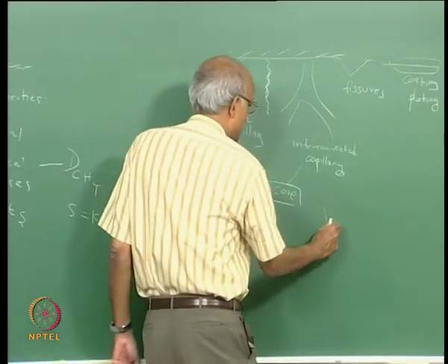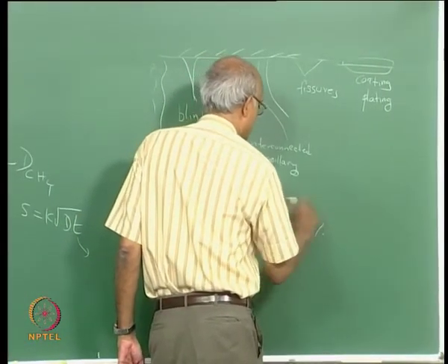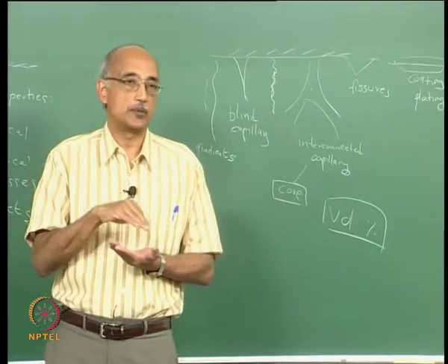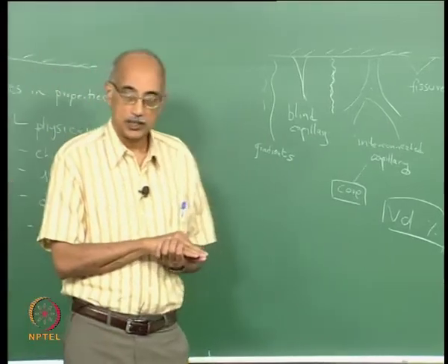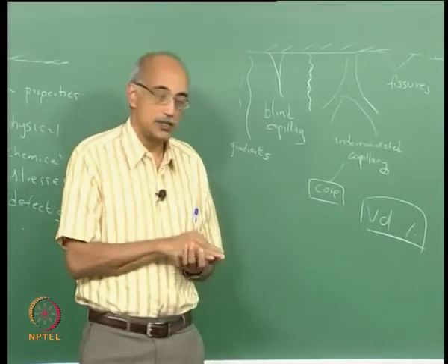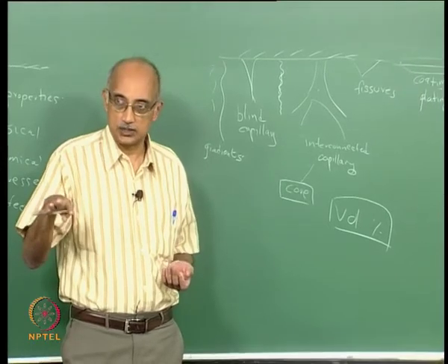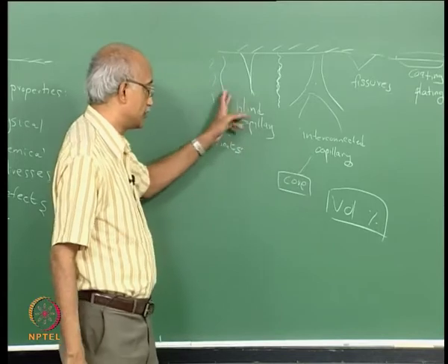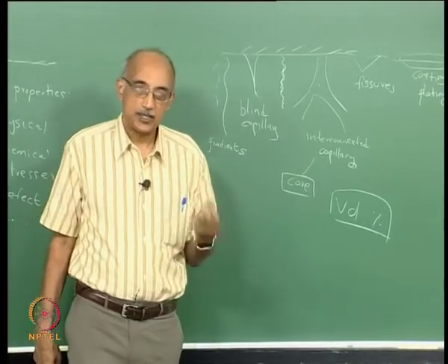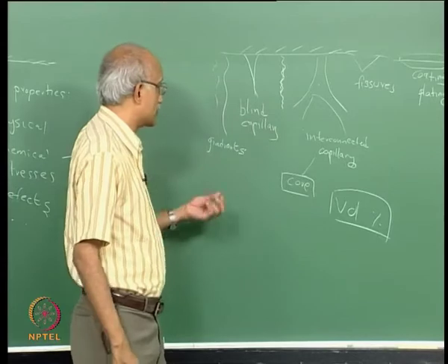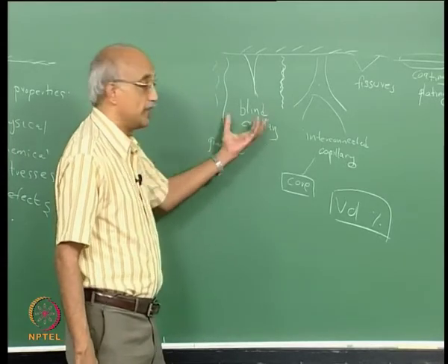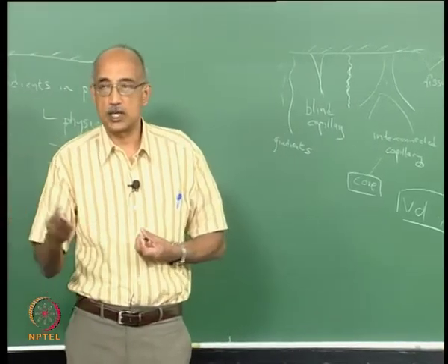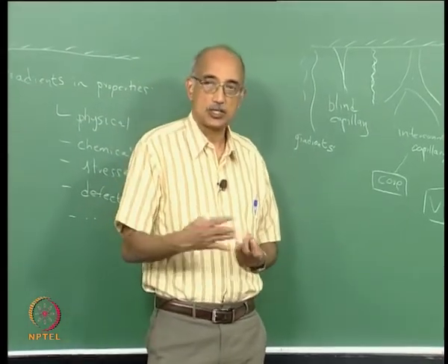So this volume percentage remains a key metric. The difference is, in the case of the surface, the volume of fluid penetration is basically dictated by its ability to fill the 3-dimensional structure which represents a surface, whereas the volume percentage of fluid in the subsurface region depends on the nature of the subsurface. For example, how many capillaries exist, essentially how many paths exist by which fluids can enter using surface tension as the primary mechanism.